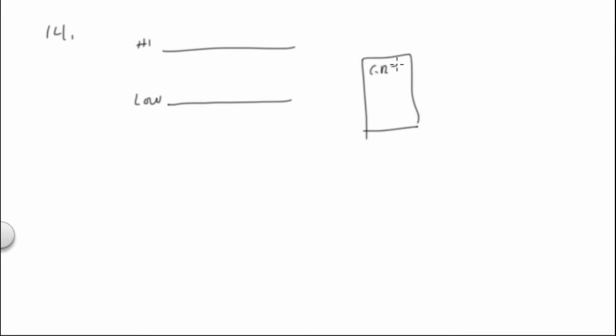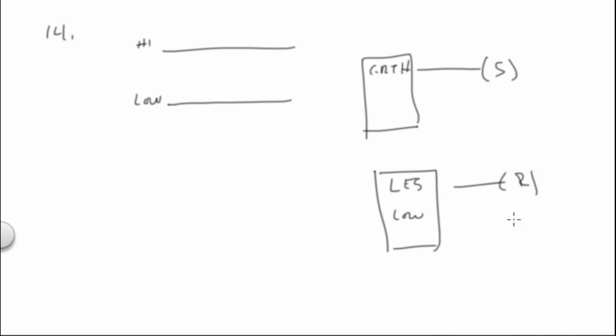Greater than high, I set my set point as the low. Okay, I turn on, I do a set. And when I go below my low, I do a reset. That kind of thing. That's how that works. So this would be for cooling, or it's up to you. If you want to do it the opposite, it would be for heating. But that gives you an idea of how that would work. One of the ways that would work.